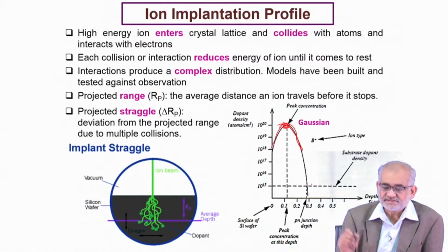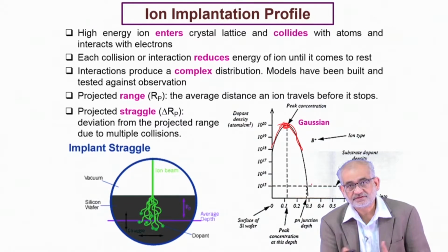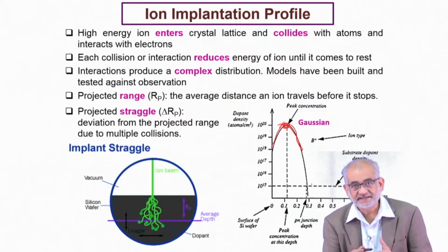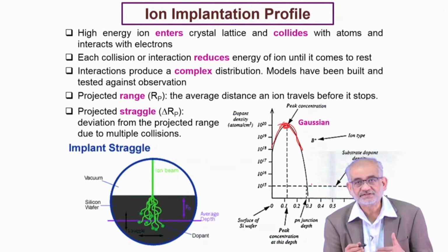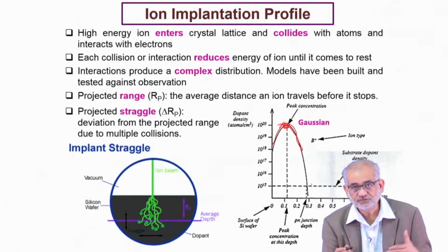And in most of the cases, the wafer or the metallic substrate or ceramic substrate on which you're implanting is not exactly 90 degree to the beam, but maybe a few degree inclined to the incoming beam from the normal incidence. This is just to make sure that there is no ion channeling. The ions don't move through and through.